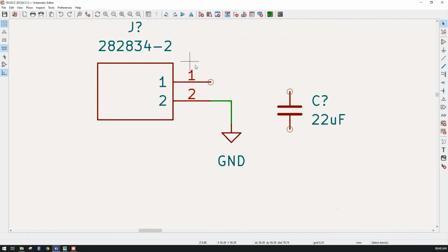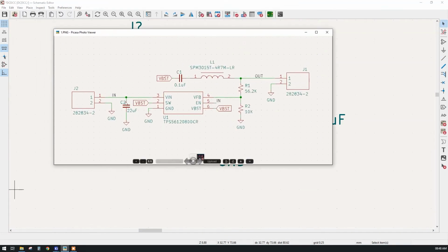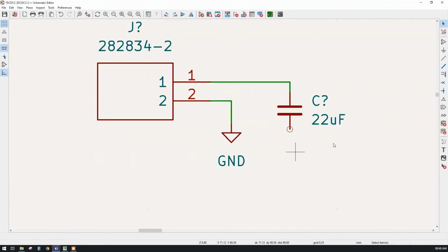And in this particular KiCAD 6 version, if you hover the mouse here on the point, it will show this green plus sign and line sign. You can automatically connect with the net simply. Okay, now what we want in the second page. Okay, so this capacitor is added and this ground is added. Now we want to add this ground. Okay, so just click on it, Control C, Control V, paste, connect.